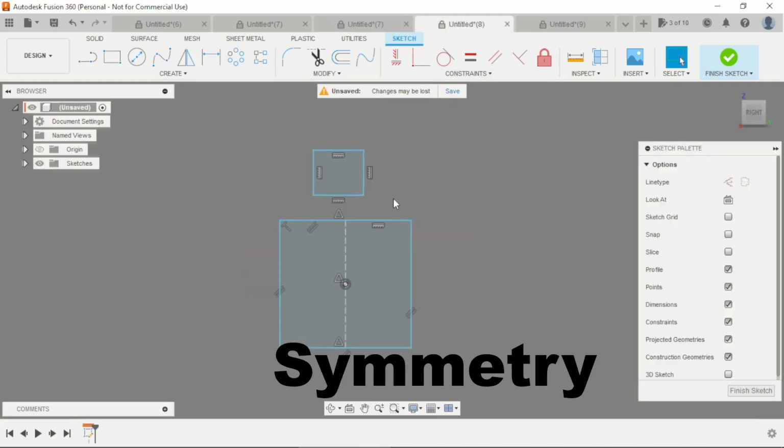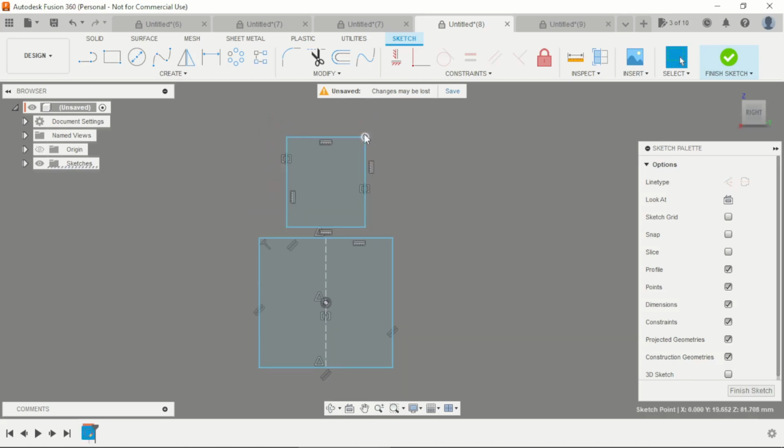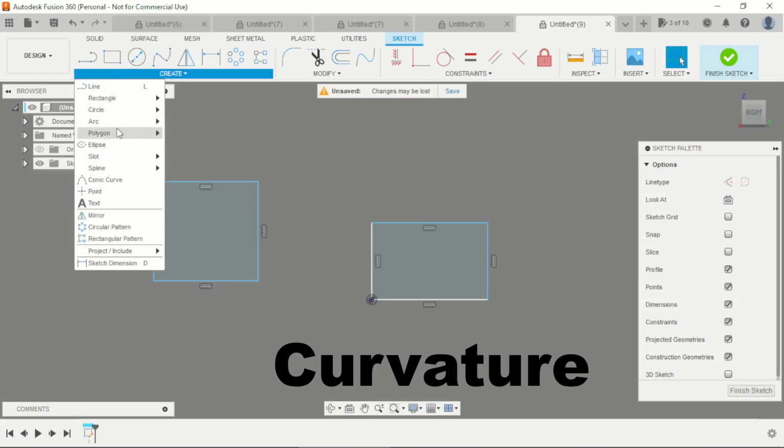To apply some symmetry, we can select the symmetry. In this case is when I want to make these two lines here remain aligned with the center line of this square. I can select these two lines and select the turn here. Now we'll have a relation of symmetry. I can resize this rectangle, but it remains symmetric.